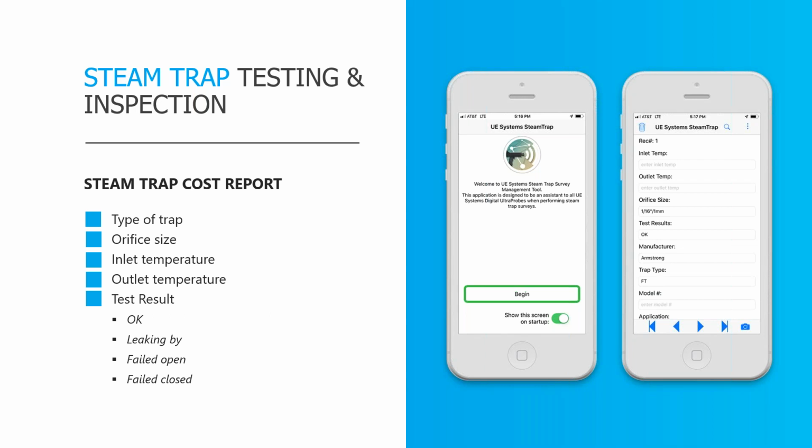So what happens is as the level of condensate changes within the trap, that produces that modulating continuous flow sound. So again, your sound characteristics with ultrasound when it comes to steam traps will either be on and off, or hold, discharge, hold, like your inverted buckets, your disc, your thermodynamics, or continuous flow or a modulating continuous flow like your F&T traps.